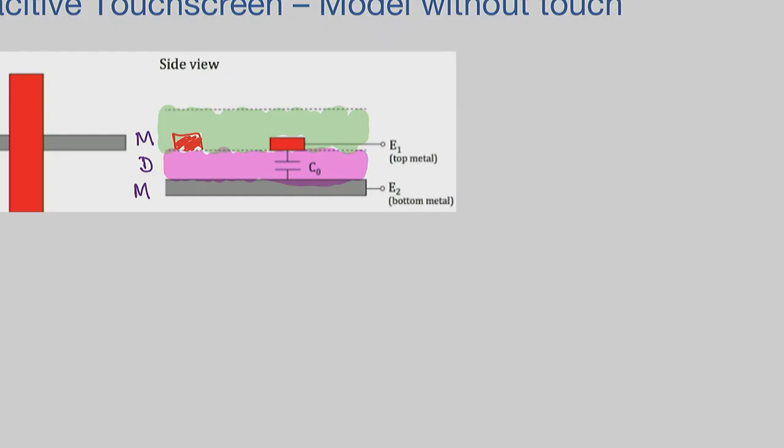What do you touch when you use capacitive touch? Glass, exactly, glass. Chances are this is built starting from glass, deposit metal grid, deposit another dielectric, deposit other metal grid, flip it, connect with the rest of the electronics, and you're interacting here, okay? This is how capacitive touch screens are made in a simplified way.